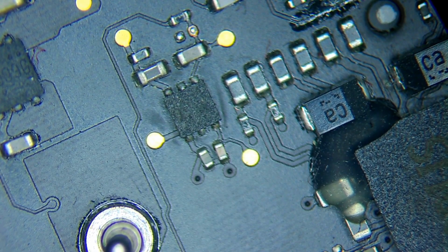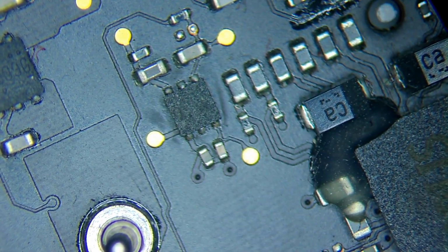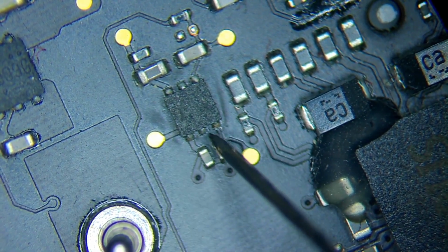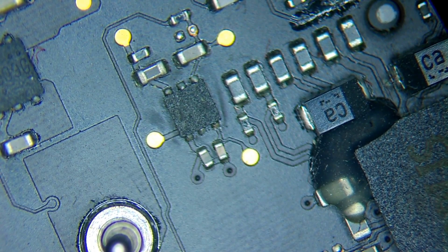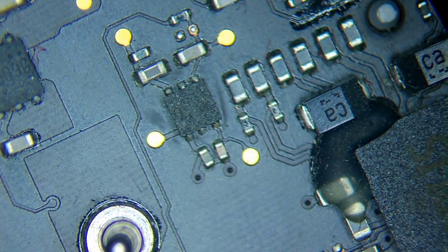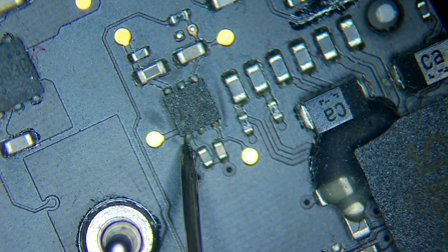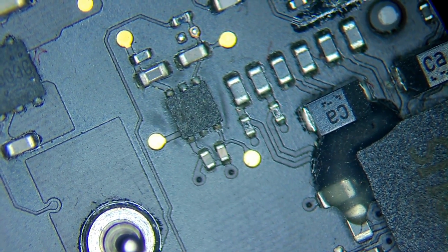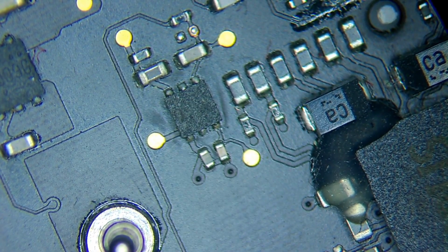Okay, so the first pin is the 4.5 volts output, and the next one is ground for the audio codec, so this should go to ground, as you can hear. And then we have the first pin, which is the PP4V5 audio analog, and it's shorted, not fully shorted, it's 0.33. So this pin right here is shorted, which it shouldn't be.